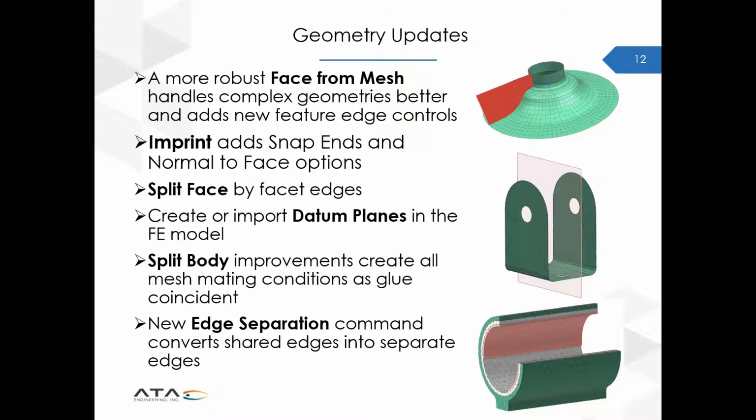Next up, we have datum planes that are now available in the finite element model. This is something that I'm pretty excited about too. So you can either create a new datum plane in the model, or if you have a datum plane in your part or your idealized part, you can import that just like you can copy over nodes or points and curves and things like that.